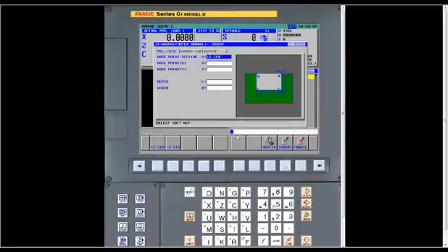And what's good about it is, like here, it's asking you where you're defining the geometry of your groove, either Z minus or Z plus. So it just depends on how your print is toleranced, whether it's giving a dimension to the front of it. So it makes it very powerful. You know, a lot of them, they always go to the back of the groove. With this, you can go either way.